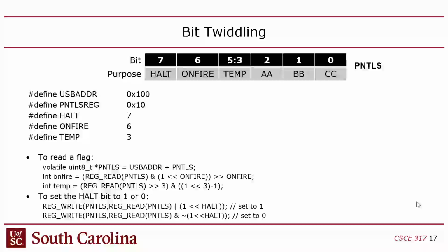You don't have to typecast these things as pointers. You just add two integers and you can assign it to a pointer, and compilers are typically fine with that, right? Now notice these are all magic addresses. You're not supposed to use magic numbers in your code, but these I/O addresses are the one exception to that rule because, like I said, they're baked into the hardware. They literally can't change, so it's okay to use magic numbers here. Magic numbers anywhere else in your code isn't good.